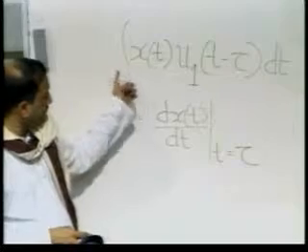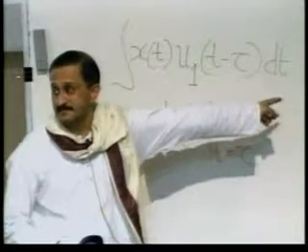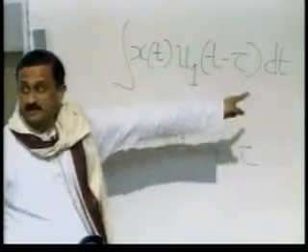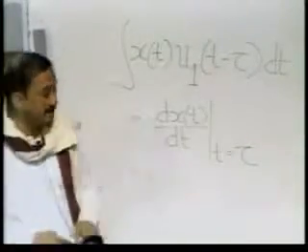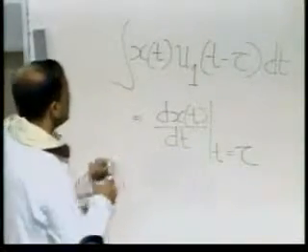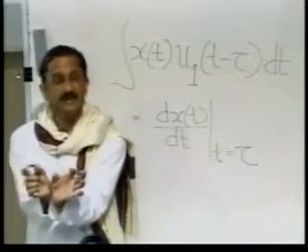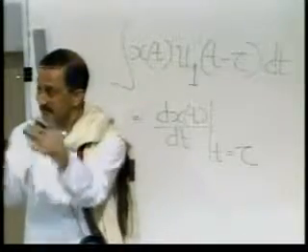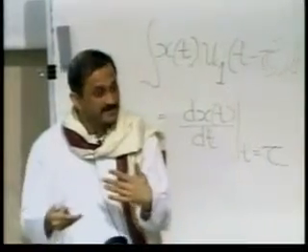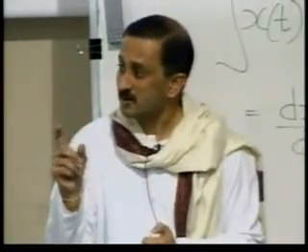No, not multiple. The question is whether there should be a product. No, there is no product of delta(t) here. See, we've already integrated. Take the analogous case if you took u0 here and you integrate. What have you done when you integrate? What is this object doing really? This unit doublet is picking up x(t) at two points very near tau, taking their difference, dividing by delta, and taking the limit as delta tends to 0. That's essentially calculating the derivative at t equal to tau. So, if you look at it that way, the unit doublet makes a lot of sense.